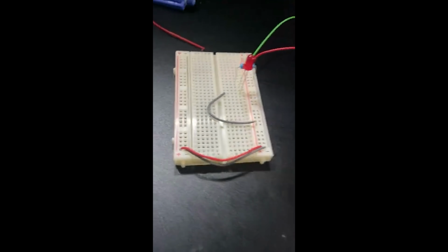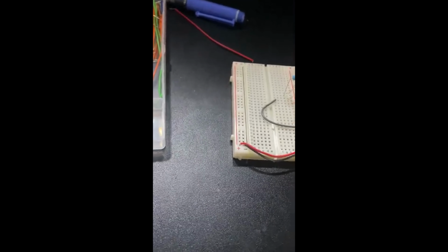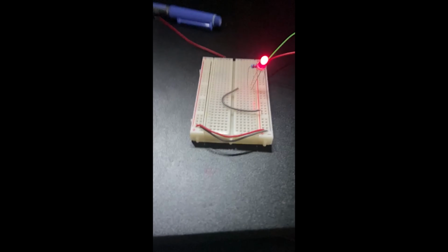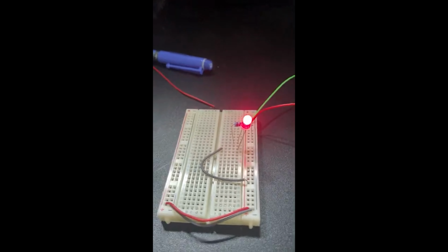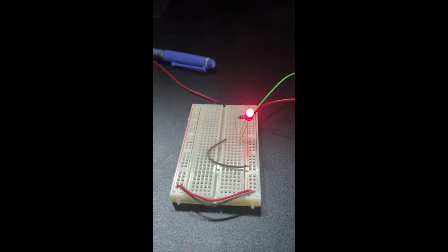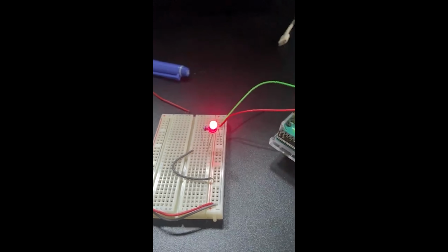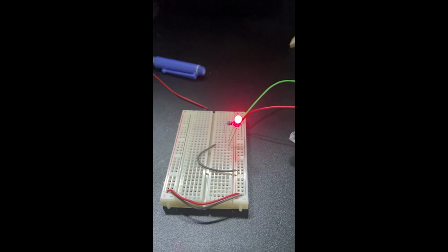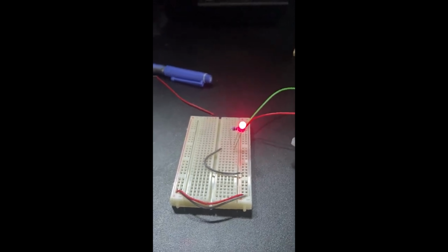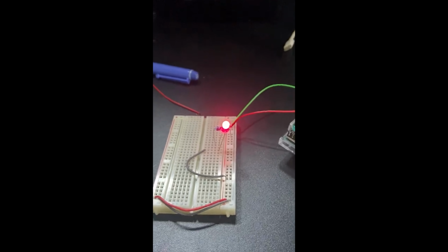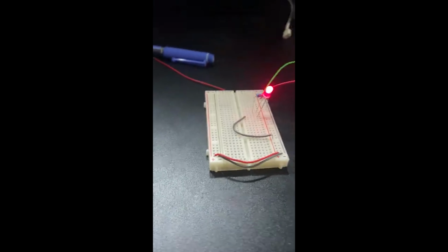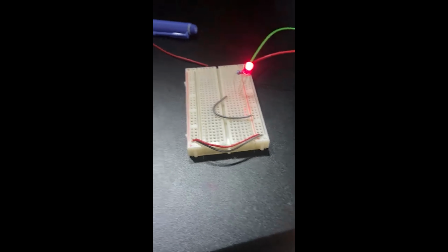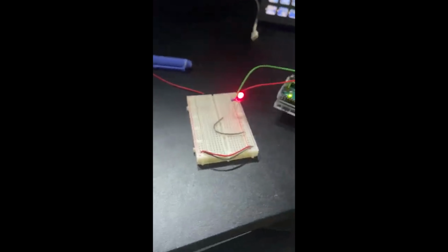Again, if we stuck the LED in backwards, nothing would happen. If we had a much smaller resistor, you would notice the light would be brighter, and if it was a much larger resistor, the light would be a lot dimmer. So I find about 220 or so is a decent one for working with LEDs. There's math involved for working this out, but that might be a little on the lower end. I've seen 270 is pretty common, 320 is used. Again, somewhere in that ballpark, and you should be fine, and you won't have anything popping on you. Okay, so that's the first bit there.